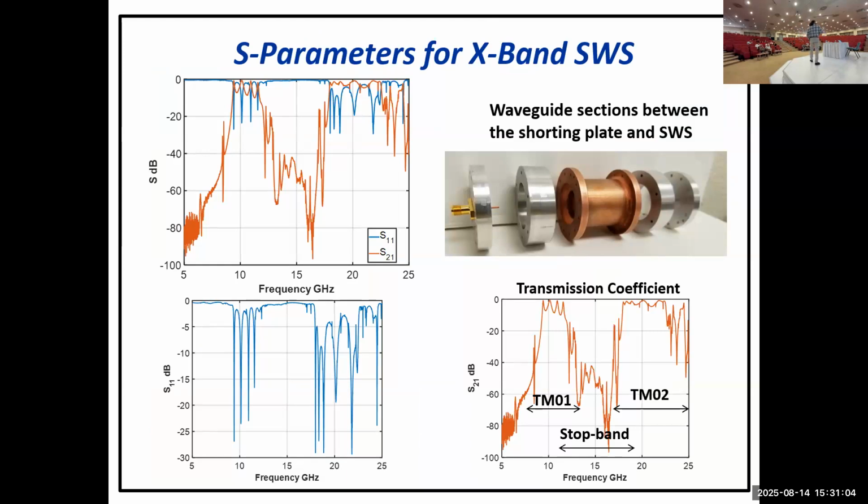So we had to have a small drift tube, probably a couple of lambda in length, and we excite this with the TM01, TM02, TM03. This structure is overmoded, TM03, because at higher frequency you get a smaller cross section. So we had to have TM03 operation of this design.